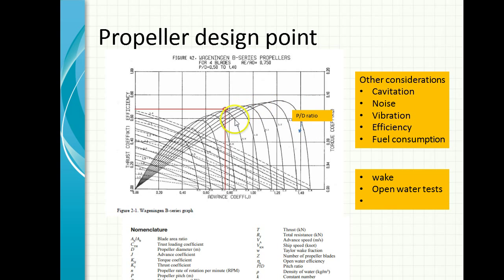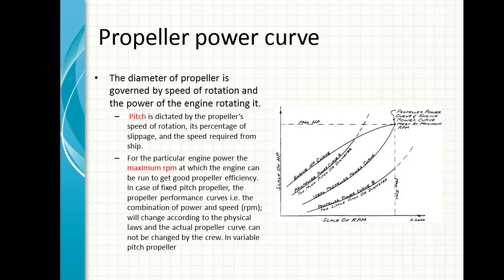And in this case, when you design a propeller, there are aspects like cavitation, noise, vibration, and of course one has to look at fuel consumption. That again is an interplay between the propeller and the engine. So all these aspects have to be considered. I will not dwell deeper, and there are quite a few parameters of a propeller you see out here, and if you are interested in knowing more, there are many articles on the internet where you can browse and know more. But what is important as a marine engineer to understand is the propeller power curve and its interaction with the engine curve, and the fixed pitch propeller and the controllable pitch propeller. I will just touch a few key aspects of this.